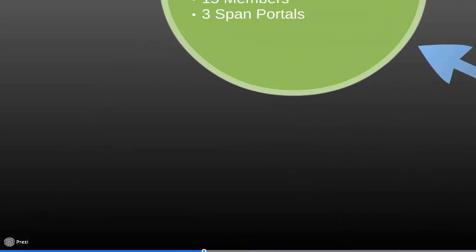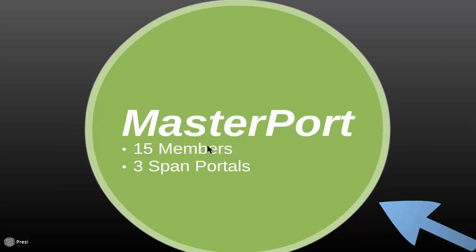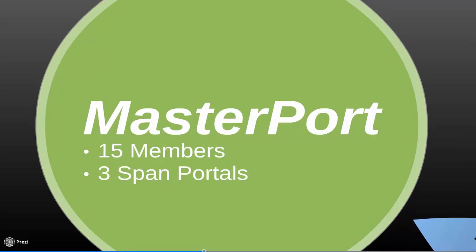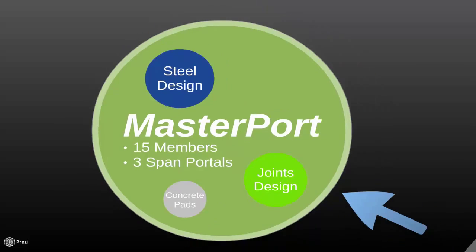And if we move forward, we will see then we also give you a version of Masterport. Limited 15 members, but that means you can do 3 span portals. 3 equal spans, 3 unequal spans, north lights, stepped portals. As long as it's a total of 15 members, that's okay. Sorry, wrong click. And that again integrates in through to do your steel design, to do your concrete pad foundations, and to design all your connections in your frame. So that's the 2 principal analysis engines that we utilize in this PowerPad.